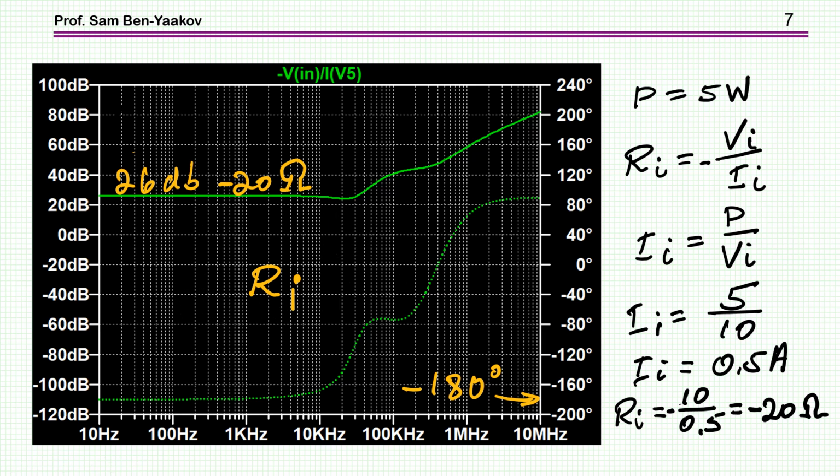Notice that the incremental resistance corresponds to the bandwidth, that is the control or the phase compensation that you have in the network, because when the loop gain drops below 0 dB, then you lose the ability to control the output, and therefore you cannot maintain a constant power. So this is the point of loop gain being 0, the bandwidth of the control, and beyond that the impedance is going up, and the phase is now changing to be positive because it is actually looking at an inductor with the phase corresponding to it.